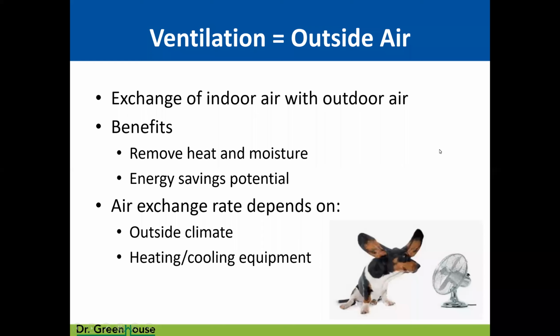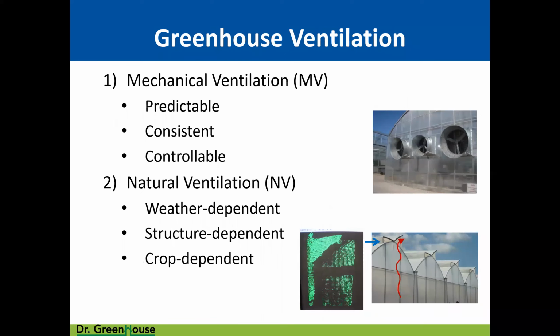Okay, so ventilation, basically it equals outside air. Ventilation does not mean air movement, it means outside air, okay? And again, we're exchanging indoor air with outdoor air, we're removing heat and moisture, and there's energy savings potential, okay? How much we ventilate and whether or not we ventilate depends on a couple of things. One, what is the outside climate relative to the inside climate? And what other heating and cooling equipment do we have available?